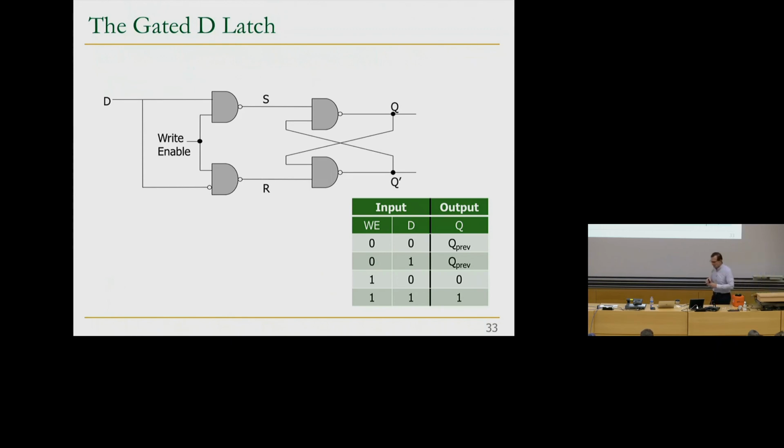We have a problem with the two NAND gates on the left taking a slightly different amount of time to react to disabling or anything like that? Yeah, but you will eventually settle. Assuming you're starting with a correct value over here, like Q and Q bar are complementary, you'll eventually settle. We'll see this in timing. Let's see that in timing, okay? Any other questions?